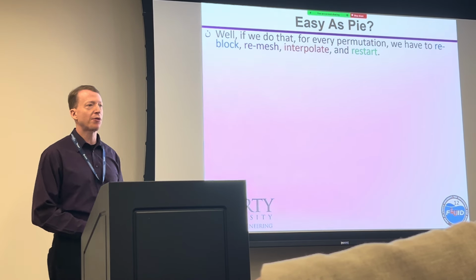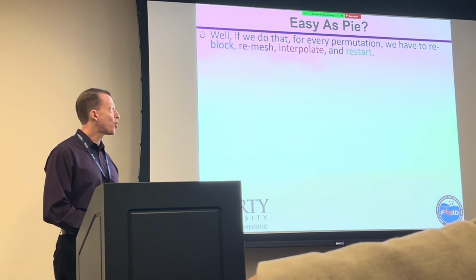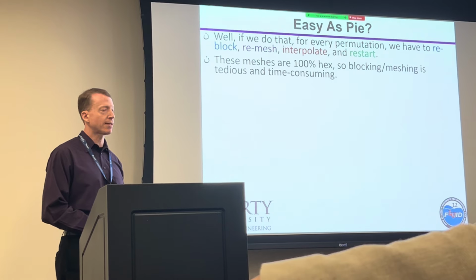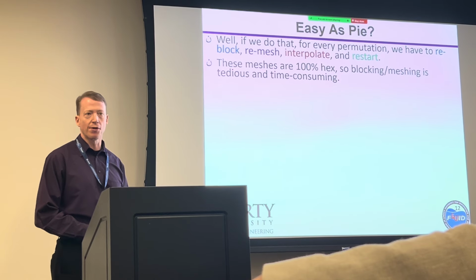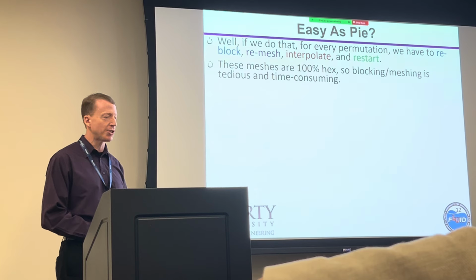Every time we do a geometric modification, it's going to require reblocking, remeshing, interpolating from prior data, then restarting that CFD model. The meshes are 100% hex. They're not cut cell. Part of the adaptation is, but the base mesh is not cut cell.